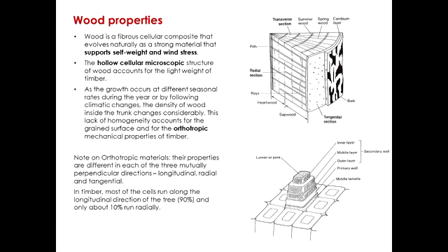You see here there are two percentages, 90% and 10%. Considering the way that the timber trunk grows, most of the fibers, or let's say technically speaking, the grain (fibers and grain are the same thing, but grain is a more technical term), will all be longitudinal. So 90% of the grain that we can take advantage of for structural purposes will be in the longitudinal direction, and 10% in the other direction.